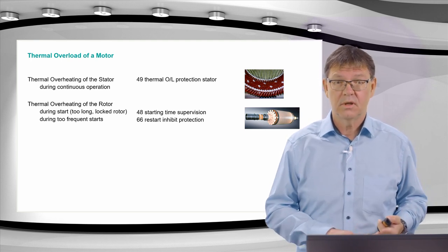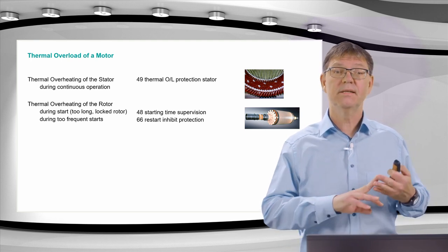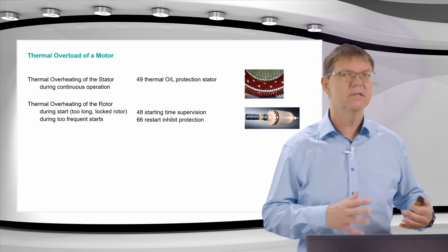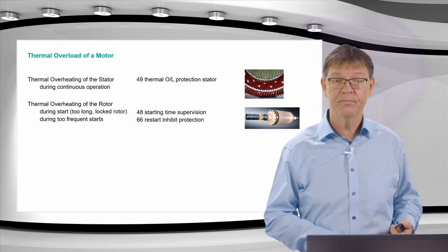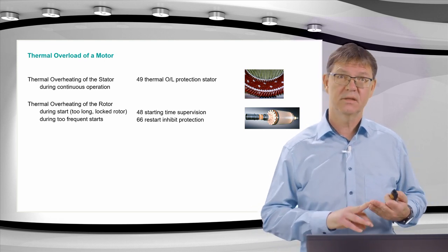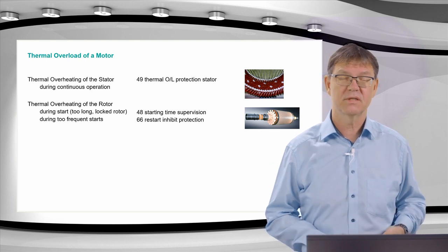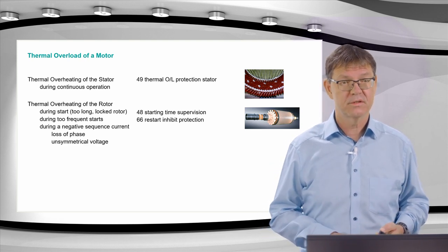Another one cares for too frequent starts, so too many starts in a certain time in a row. Therefore we have this so-called restart inhibit protection, ANSI number 66, as you see here on the screen.